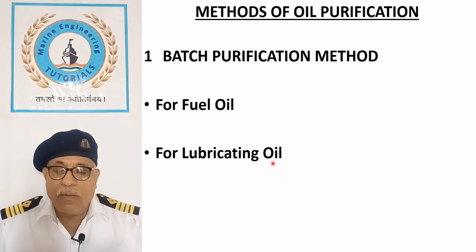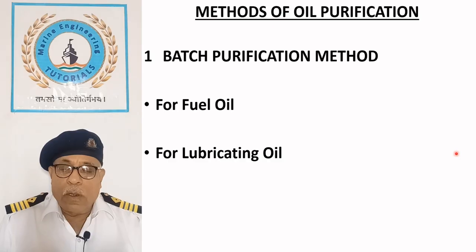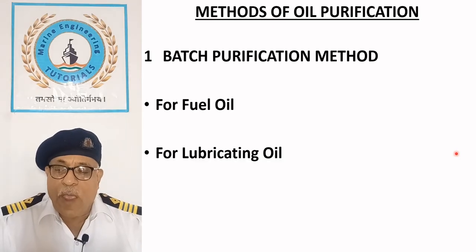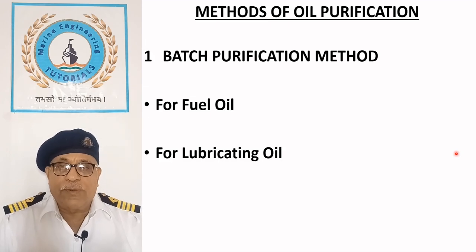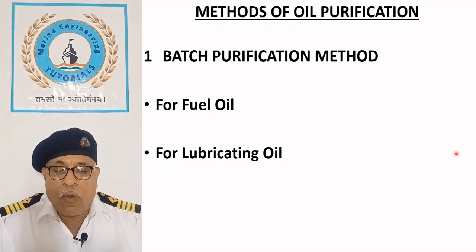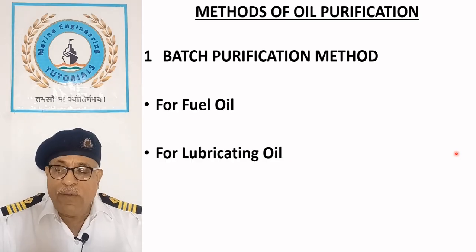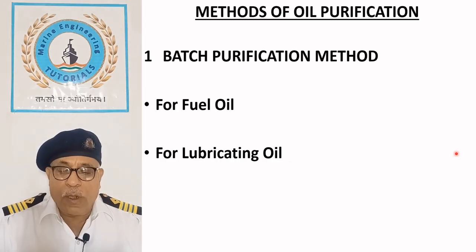For lubricating oil. Now let's look at batch purification, which is generally used for lubricating oil. This method is adopted when the lubricating oil becomes unsuitable for use due to heavy contamination with water or the formation of thick emulsion.